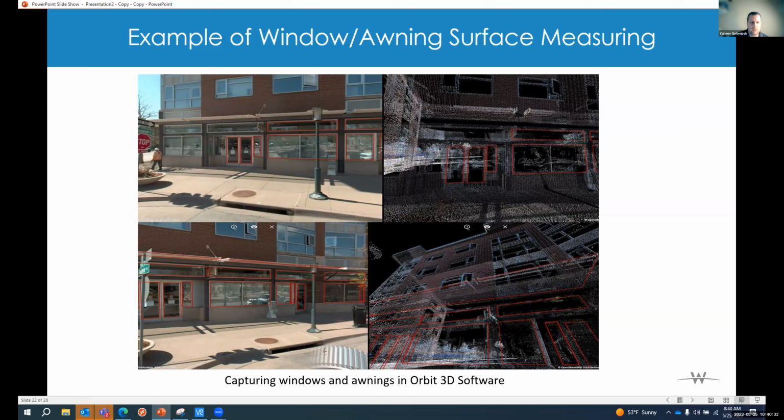And then again, with the help of Esri Model Builder, we ran a process of creating a triangular irregular network of each and every feature in order to measure what the actual surface is. Now, why did we do that? Because if I take these shapefiles and throw them into Arc Pro, all it's going to show me is a line, because it doesn't really work in 3D.